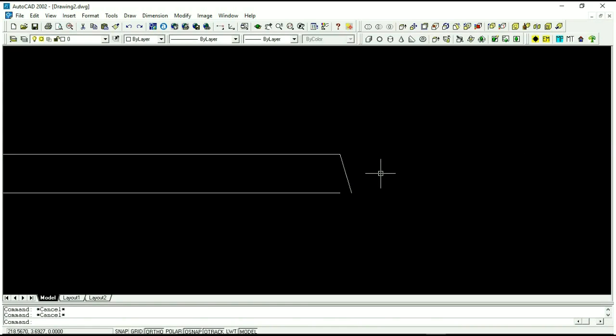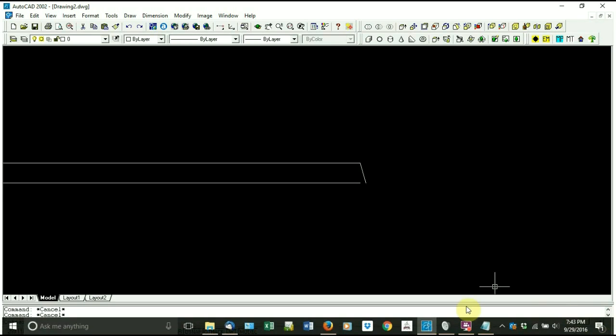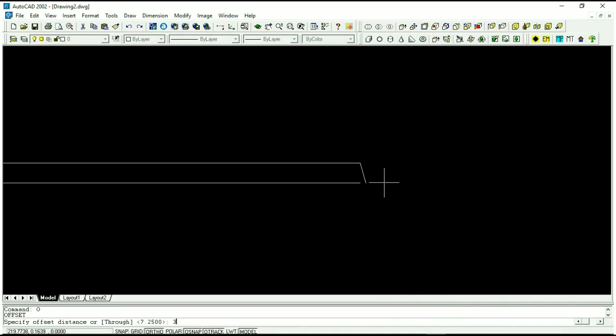tail on that. 22.5 would be the rafter run. So I want to take 22.5 divided by 12 times the hip factor, which is 17.69. And it gives me 33.16. So I'm going to offset that 33.16. And I'll let you trust me on that one. I'm not going to waste any time on the video making this any longer.